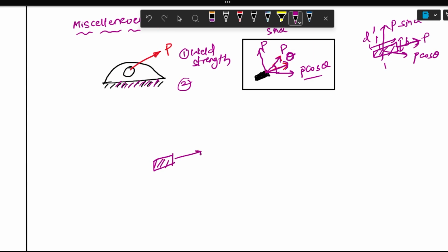The load P is acting axially across the lug plate along the major axis, and this is B, and this is D. So the section modulus is B into D square by 6. Here D is very much greater than B, so the square term is there. Anyway, the section modulus is very high in the major axis.